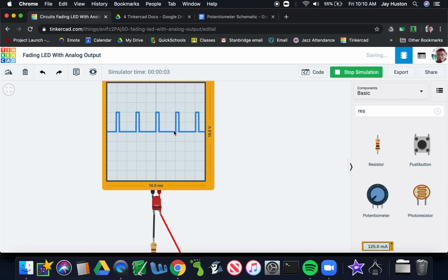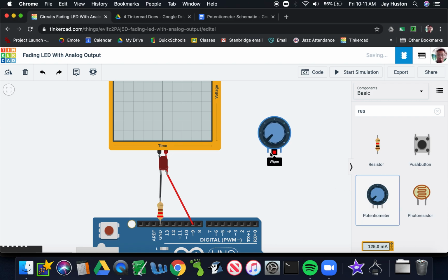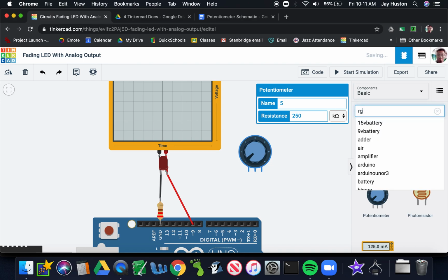Again, the Arduino only has 2 settings, off and on, and the LED is passing through the same brightnesses that we were seeing with the potentiometer, but it is doing it through mimicry, as in it is actually going completely on or completely off for different amounts of time, which is not the same as the potentiometer. The potentiometer was actually changing the volts, so it was getting brighter and darker due to the amount of volts passing through it.